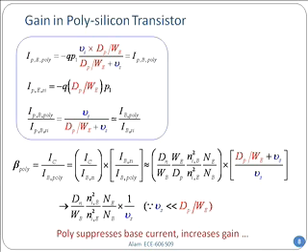Okay, so do you understand physically? Forget about the math. Yeah, this is high school algebra. But the polysilicon, how it suppresses the base current by slowing down the holes, and as a result increases the gain. And subsequently after the 1980s, this became the standard in the industry.